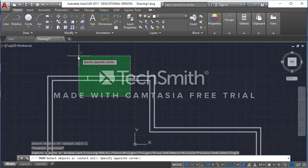So you have a little bit more selection precision by using the blue box, but if you want to select a large group as a whole, you would select everything using the green box. So again, the blue box will select only the items inside your selection marquee, and the green box is going to select everything that is touching or going through the green square, okay?